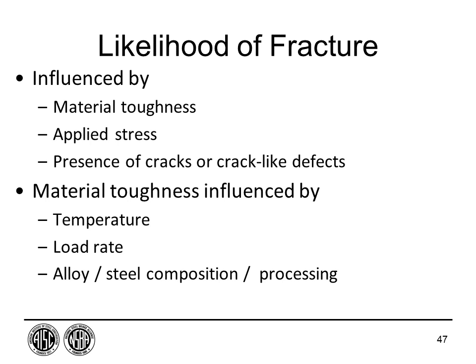So we talked about likelihood of fatigue. Well, what about likelihood of fracture? There's one term here that we didn't talk about in fatigue, and that's the material itself, specifically the material toughness, or its ability to tolerate cracks. That's basically, is it brittle or is it a ductile material? Then there's the applied stress in the material, including residual stresses. And for fracture mechanics or cracking to occur, sudden brittle fracture, you generally have to have some kind of a defect, whether it's a crack or something that's just like a crack.